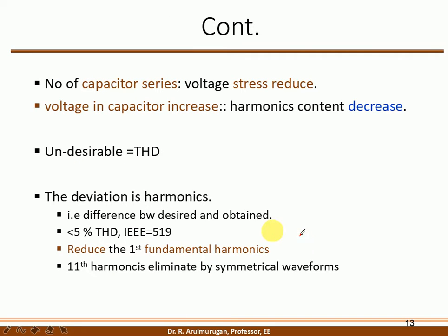And then the capacitor is connected in series. The capacitor, as we discussed, is connected near the source side, to reduce the voltage stress level. When the voltage in the capacitor increases, the harmonics content decreases. So increasing the capacitance voltage decreases the harmonics level.